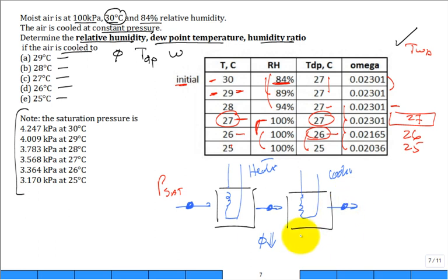And they thought that was dehumidifying. Do you think that's dehumidifying? Nope. Not at all. So they were fooled. They thought this heating was dehumidifying. It was not dehumidifying. The omega was staying the same. The humidity ratio was staying the same. Now, if they really cooled it, they may put a drip pan right under this cooling coil, and they may get some condensate off of it right there. But this was just a complete waste of energy. Complete waste of energy. All right, let's press forward.